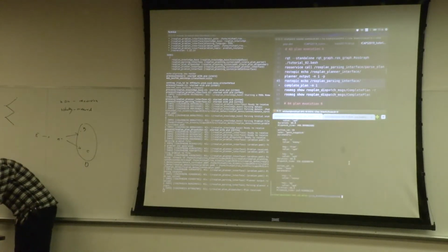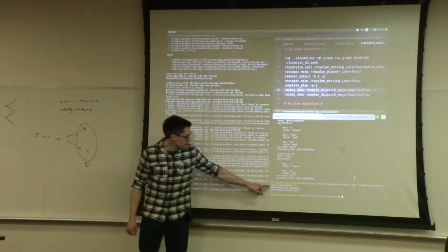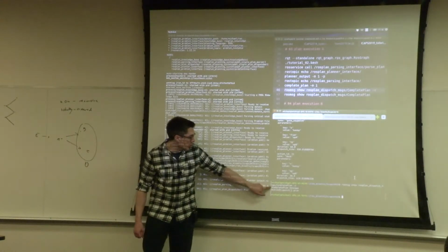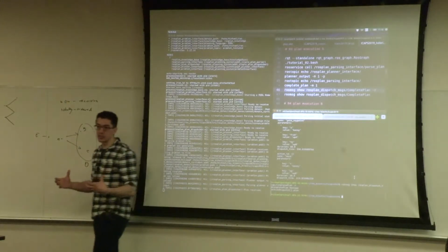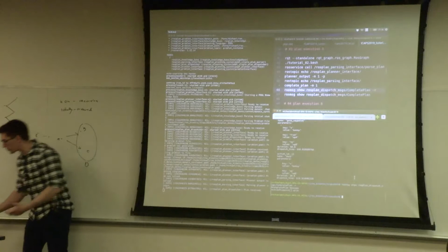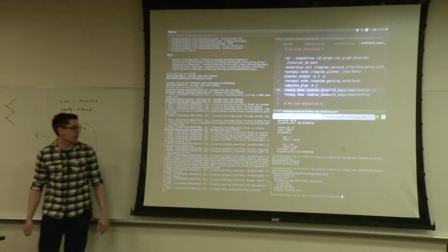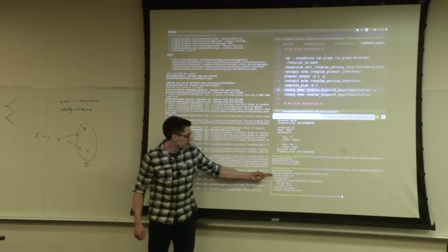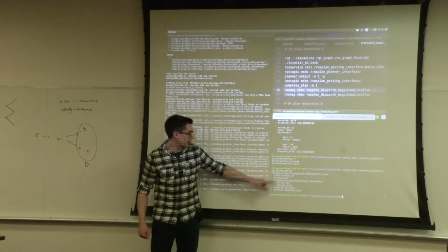So essentially, and I can show you exactly the structure, this is the complete plan message. I've just shown the message on the screen down here. It's quite small. There's a comment that says complete plan message, and then it's an array of action dispatch messages. It's very straightforward. The -R there is just to show the raw format. If I don't include the R, then it expands what is the action dispatch message, which are just these parameters we saw: the dispatch time, the duration, the parameters, and the name of the action.